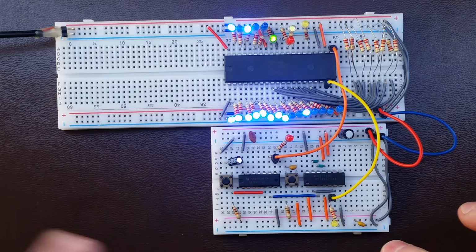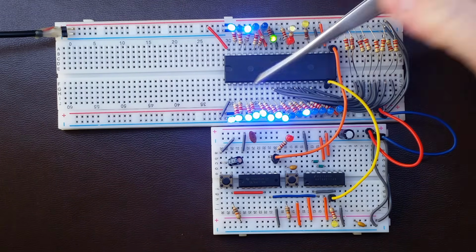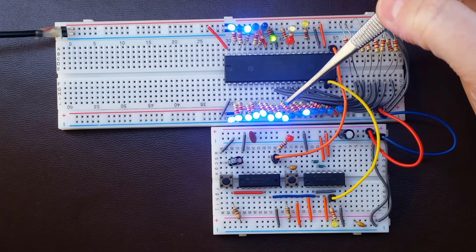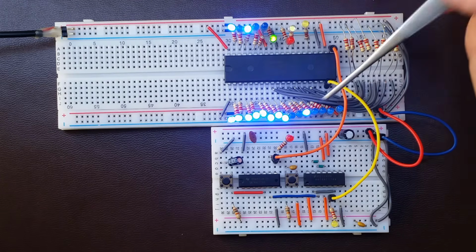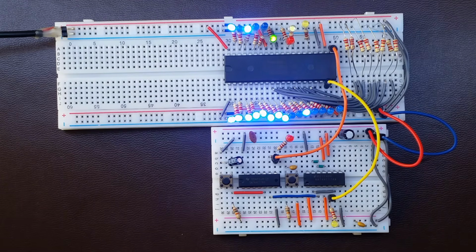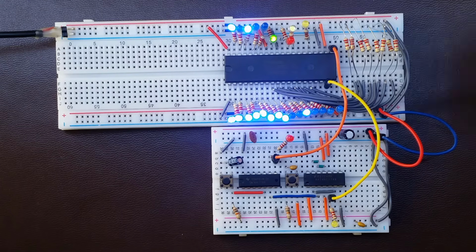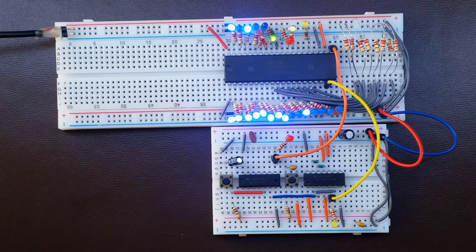What we see now is that A8 up to A15 are still holding part of the address because they are not used for transferring any data, and the most significant 4 bits are holding some status which we're going to ignore for now.